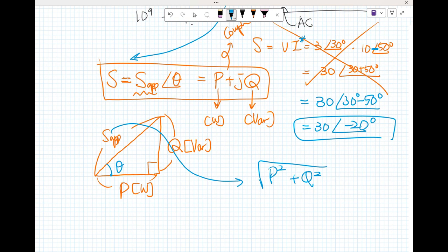So maybe it depends on whether it is active or reactive power we learned before. For positive P, we can draw the triangle on the right side, just right there, maybe with an angle. But sometimes from zero, this is the reference starting point. Sometimes for negative P, we should draw to the left, like this, but it should be the same amplitude, okay? And Q is the same thing. Q is reactive power. Sometimes the circuit or device is considered positive, meaning upward, just like this one. The upward, for example, 200 VAR, 100 VAR, 50 VAR, you have to draw upward.